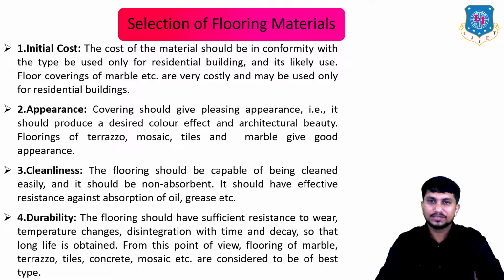Next is durability, or you can say long-lasting ability. The flooring should have sufficient resistance to wear, temperature changes, disintegration with time and decay so that a long life of the flooring material is obtained. From this point of view, flooring of marble, terrazzo, tiles, concrete, mosaic, etc. are considered to be the best type of flooring material based on durability.